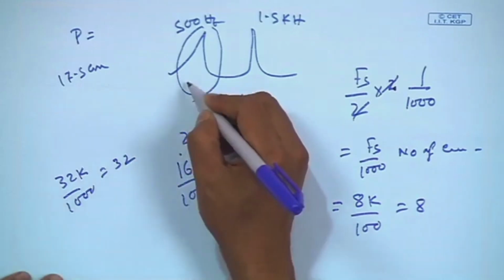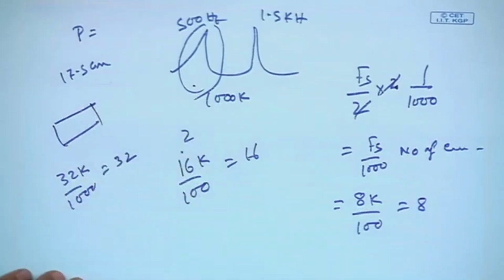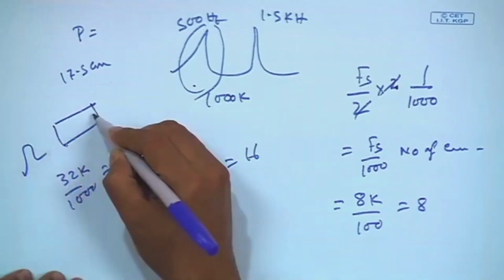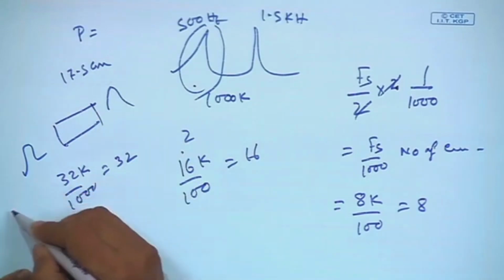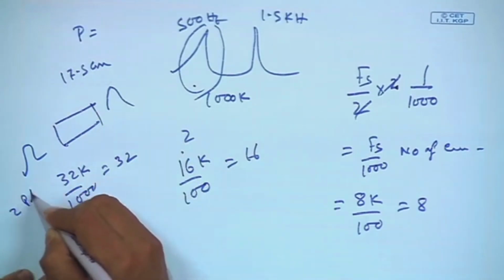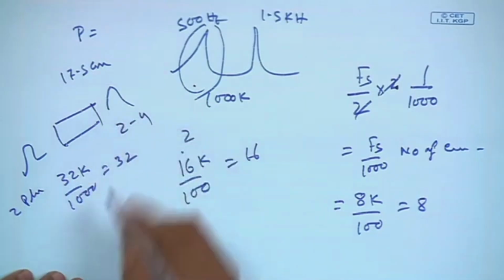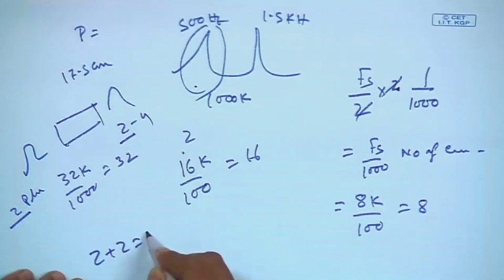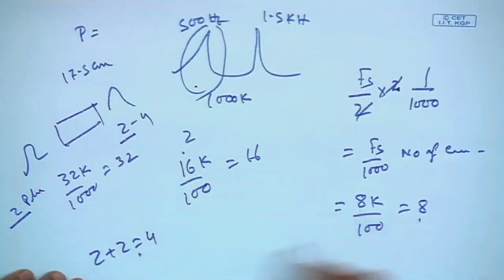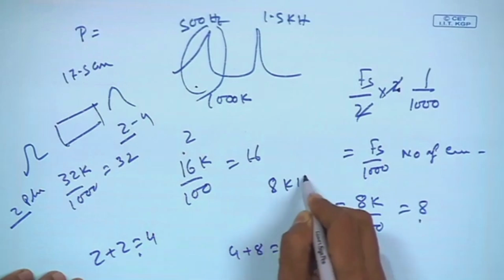So, those are for formant, that means those are for the tube only. Next, there is a glottis and there is a radiation loss. For glottis, 2 poles, and for radiation loss, 2 to 4 poles. So, if I say radiation 2 pole and glottis 2 pole, 2 plus 2 is equal to 4 pole, 4 plus 8, 12 poles if my signal is sampled at 8 kilohertz.